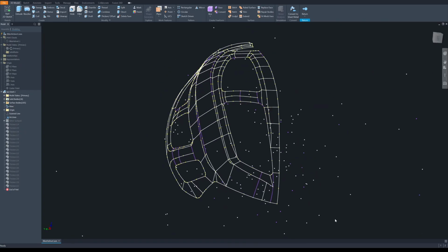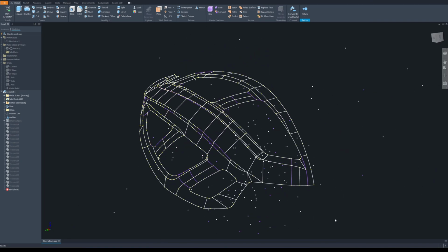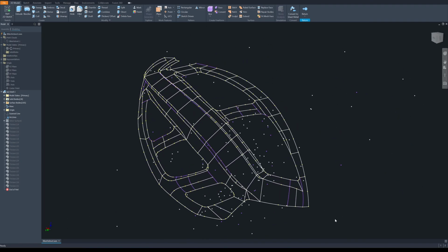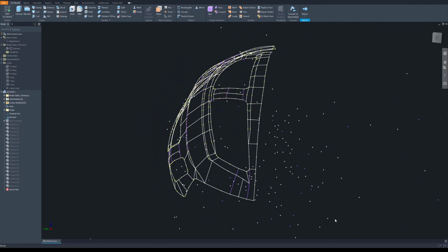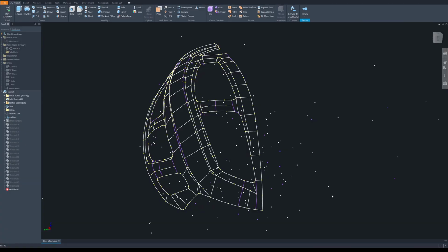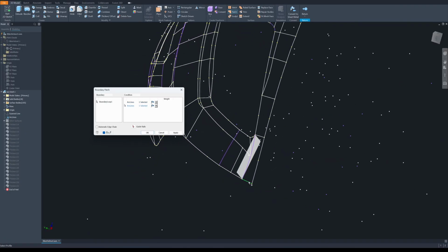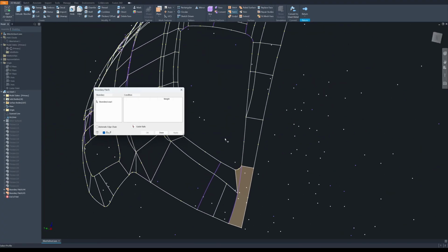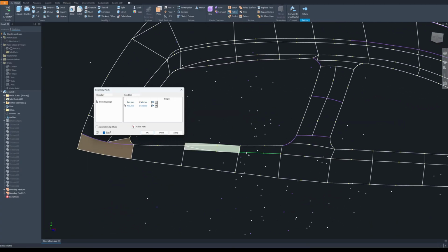To create a surface, you will need 3D lines, and what you see here is an arc in 3D space extracted from a 3D scan model. So if you can create good topology, a 3D arc like this, you can then create a surface by using the Patch command. When you click on the 3D lines and create a closed loop, then you can create a surface. It can be three sides or more. For example, I can create a very long strip like this.